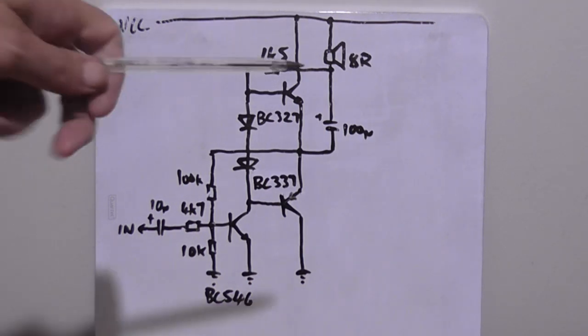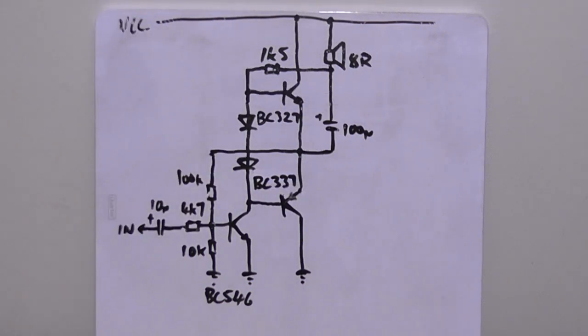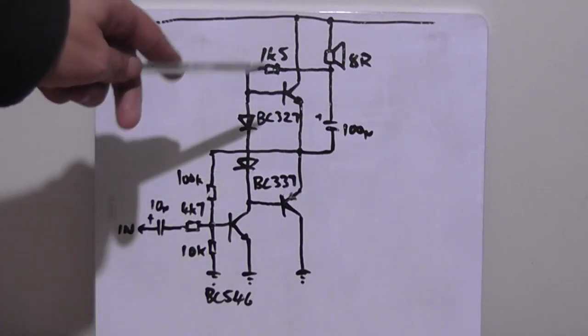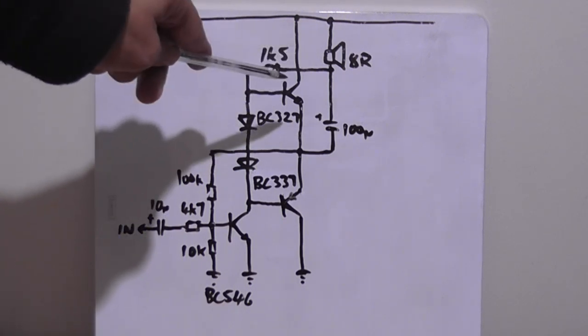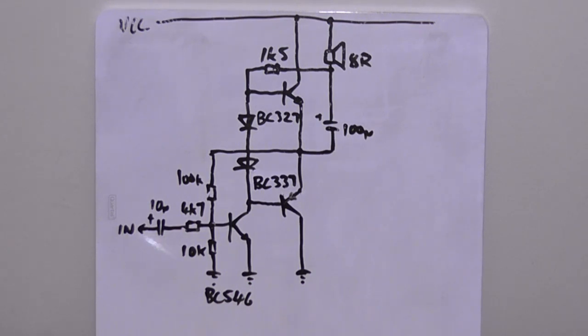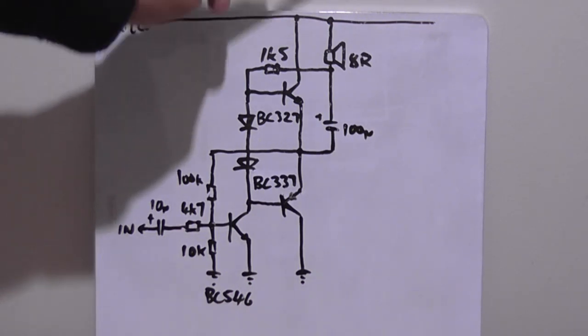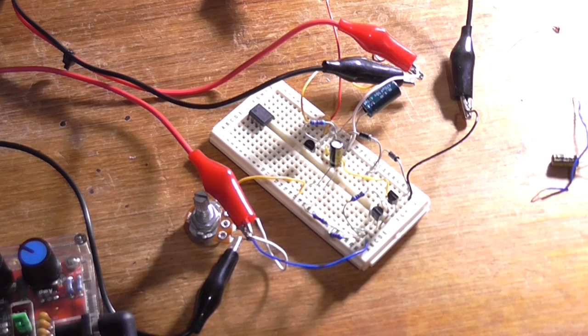So I'm going to breadboard it up, put my 8 ohm dummy load in line with it, first measure to see if the thing even works, and then worry about what's the voltage drop across this resistor. Once we know the voltage drop across that resistor, we can then calculate the current. Then once we know the current, we know how much power is being wasted through the voice coil. Sounds simple? Sounds simple. Alright, and after messing around for about an hour I've got it to work.